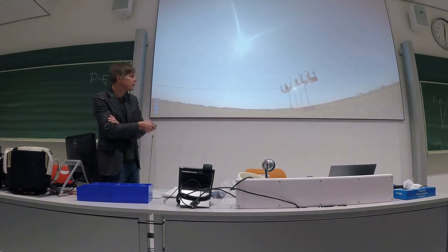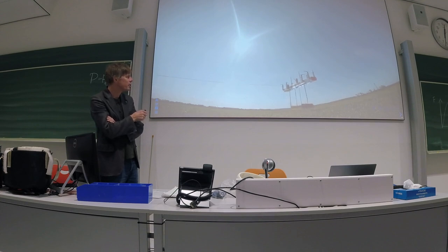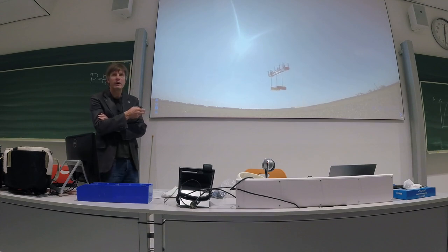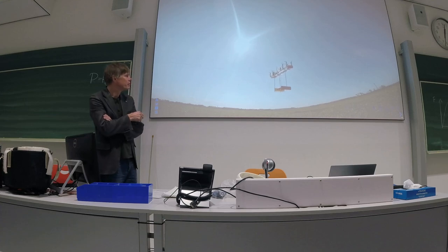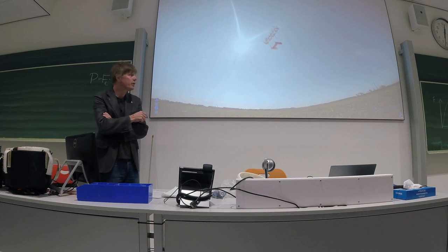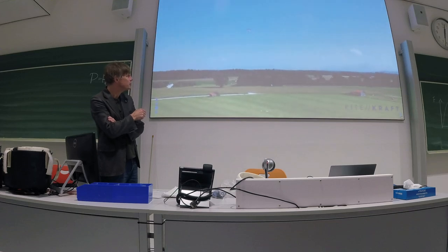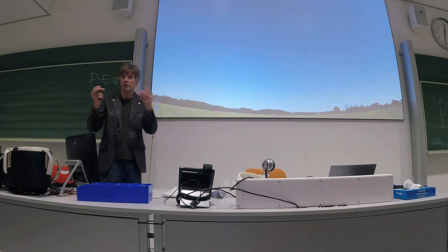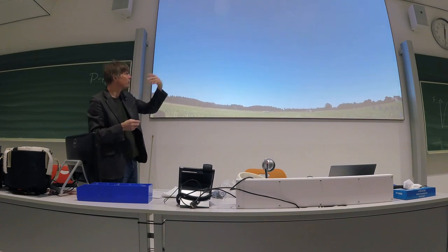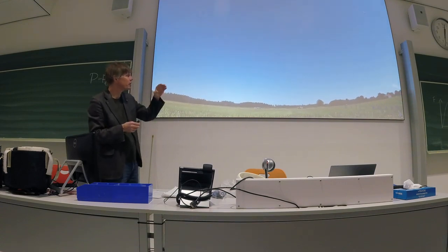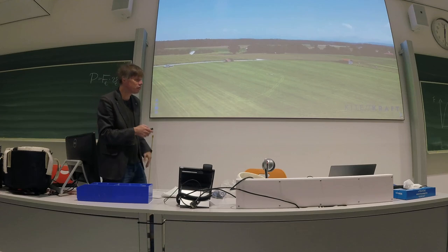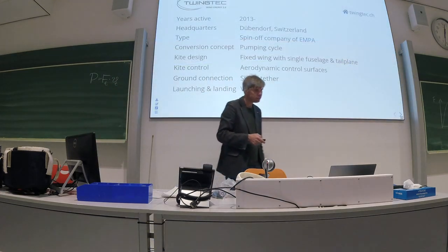So that's not the 100 kilowatt system, that's the smaller scale, I think 10 or 20 kilowatt system. You see now why it's called tail sitter. So here they just hover off. Electricity comes through the tether, and then they go into crosswind flight. Transition again between liftoff and crosswind is critical, and also from crosswind back to landing.